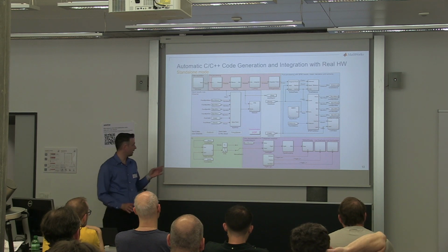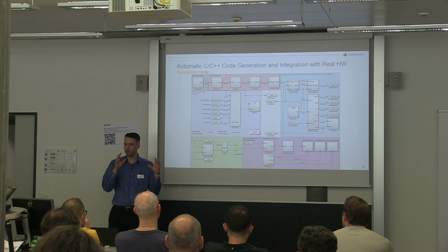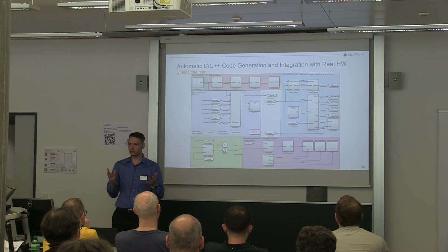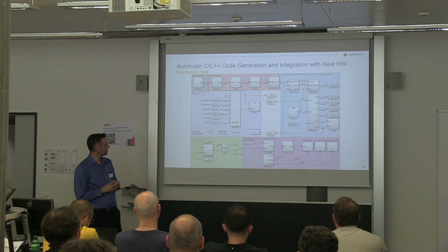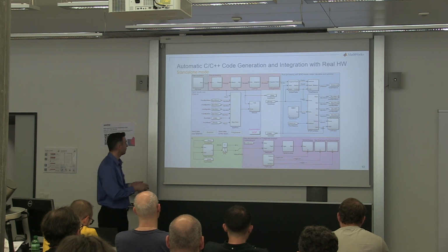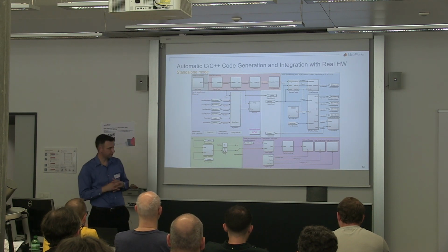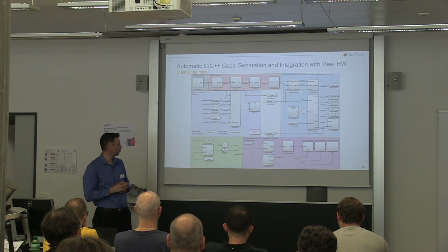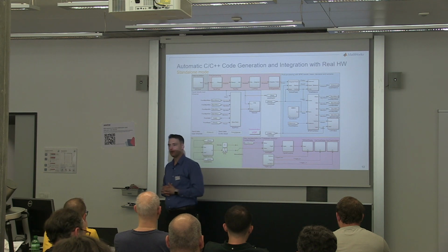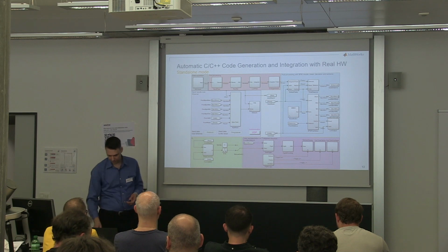Here I have then the final representation of my system. So the first one I showed you before with the components, the system, and so on, we can call it the logical architecture. This one is more the physical architecture or infrastructure architecture. And in this case, we are really connecting the algorithm to the real hardware peripherals. Like, for example, here, now my inputs are no more signals from MATLAB, but are directly signals from the ADC that is used onto the board itself. Also here I have the reset button, so this time it's not a virtual reset button anymore, but the real one onto the board. You can see it onto the board. It's the red or blue one that you have.